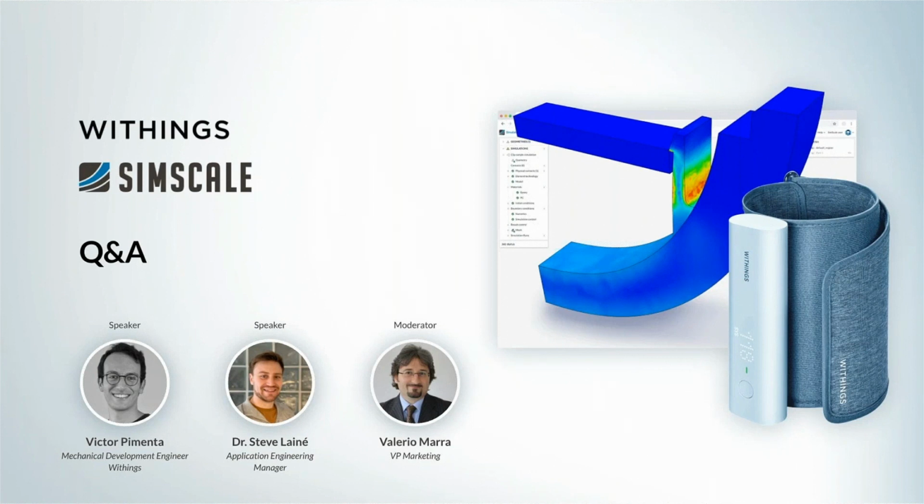For instance, in this clip, we had the head of the clip, the undercut, and that's where we tried to improve the node length and combine a good physical contact definition with a more precise mesh. In this case, it was a fine mesh. We could simulate this very quickly and get results in less than hours.